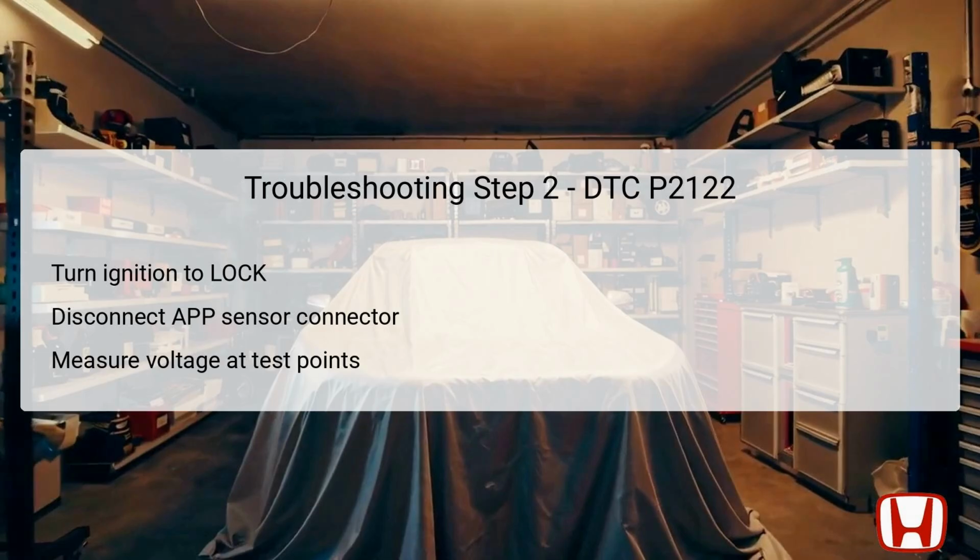With the connector removed, turn the ignition to the on position again. Then measure the voltage between test points 1, number 5, blue wire, and 2, number 6, BRN wire at the APP sensor connector. At this point, you should expect a reading of around 5.0 volts.